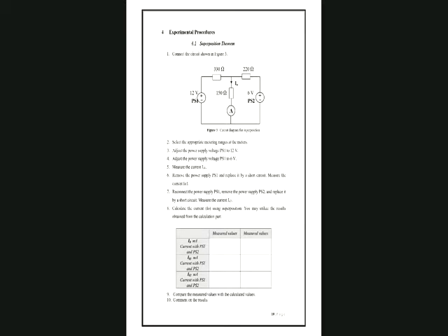Now here we just measure the values. Note down here, this is 29.7 milliampere. Then next we will find the current due to PS1, and we short circuit PS2. Here we got 17, and next I02, that is the current due to only PS2, so we will short circuit PS1.